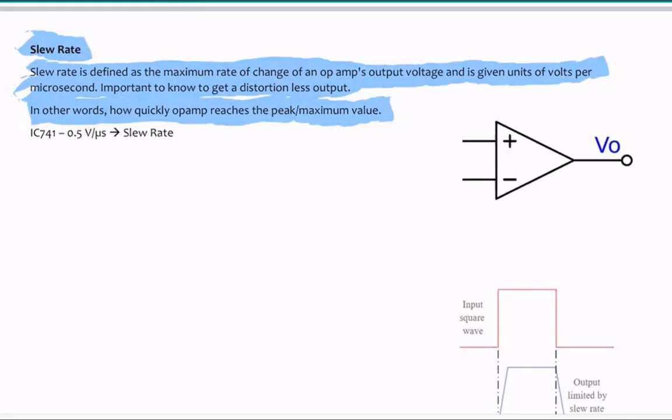Okay, so I'm going to make it very simple here. So say you have an op-amp. The positive, which is the non-inverting terminal, is connected to some input, and then this negative terminal is basically connected to the output voltage over here. And because the output voltage is connected to the negative feedback, your Vn is going to be whatever the output voltage is there.